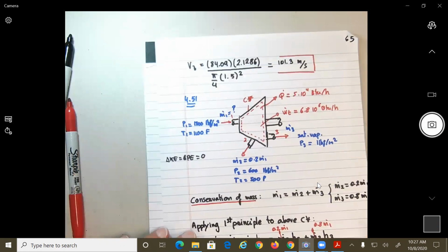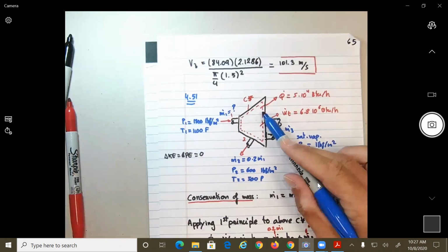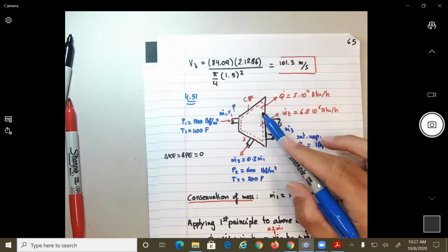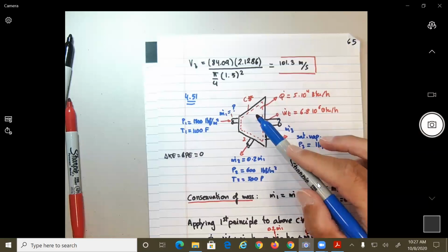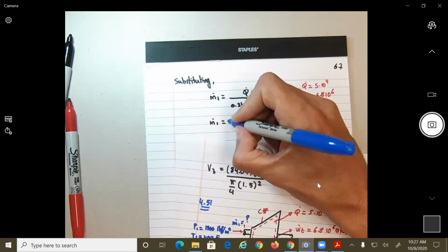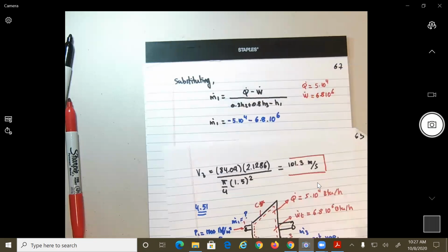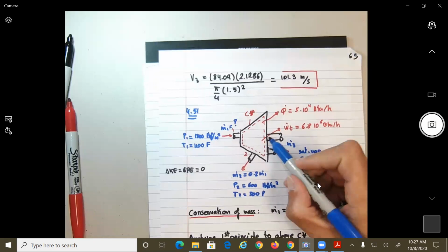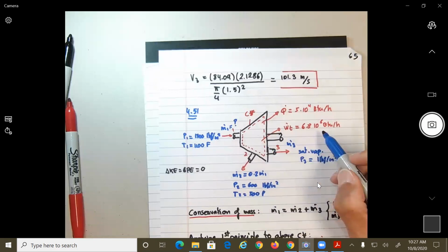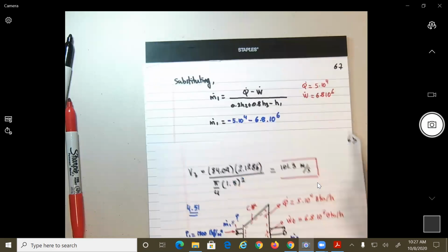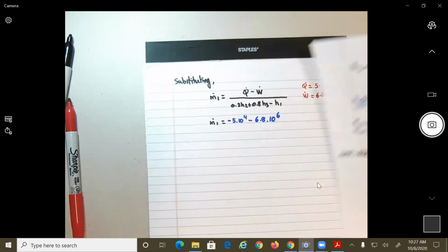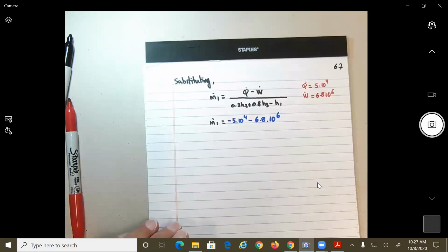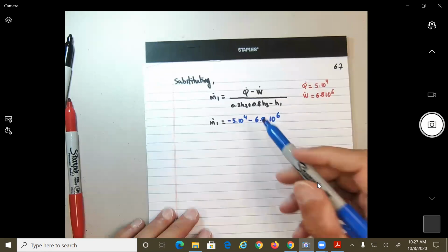Remember the sign convention, if the heat is going out over here, is that positive or negative? This should be negative, no? Heat going in is positive, heat going out is negative. So maybe you should put here a negative sign. And now, work done by the system is positive, on the textbook sign convention. So we should have then both of these negative. Hopefully we just have to take the magnitude, or maybe this is going to become negative. We'll find out.